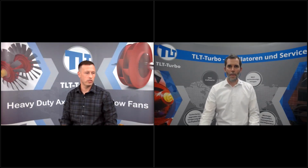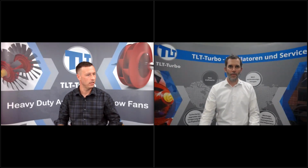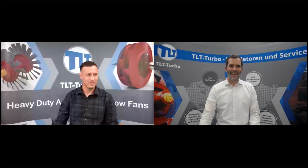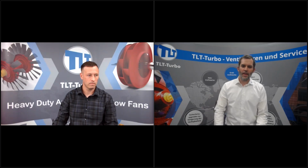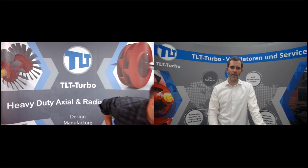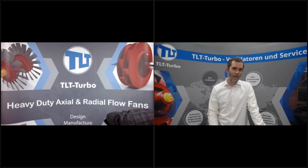Okay, so the question is, for the Al2O3, is the wear material a blend of materials, and how is that application applied? Sorry, there's a train in the background. The wear materials are applied by screws, bolts, or you can also weld them in. And then you can exchange your wear plates.